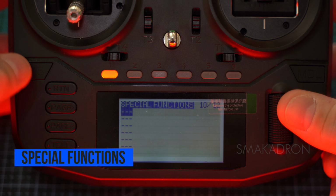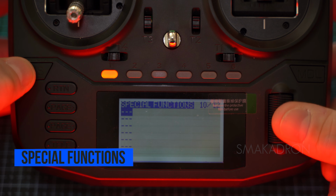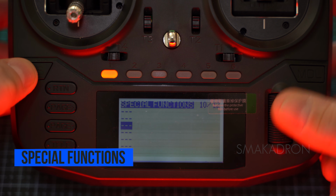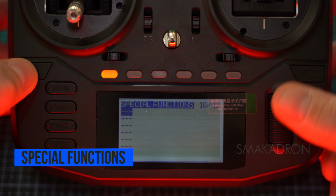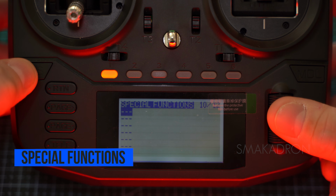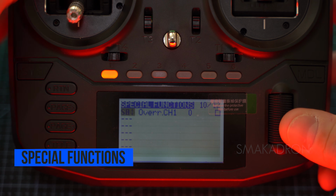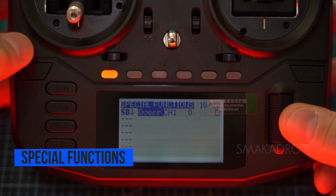This section provides additional functionality that allows for more detailed model configuration. These functions can include enabling trainer mode, playing sounds, adjusting the radio's backlight, adjusting the volume, and many other possibilities. Let's create a new function. Click on the dashes. For example, I want to activate something with the SB switch in the down position.